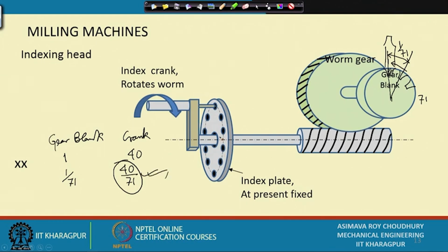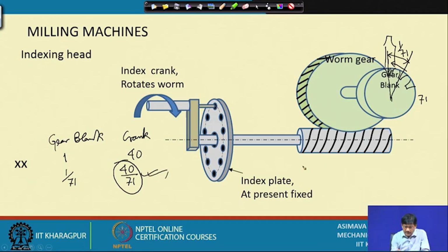So, you will say, why 71 has not been included? That is because you might be having the requirement of having numbers of holes varying from 1, to 1 is of course hypothetical, say varying from maybe 17 or 15 right up to infinity. So, for the initial prime numbers you can have them covered. If you are taking say for example 20, this covers 2. If you are 20 hole circle, this takes care of 2, this takes care of 5, like that. So, if you are taking 21 holes, that takes care of 3, that takes care of 7. But 71 has not been included because it is not possible to include all the prime numbers, they are unending. So, this is left out.